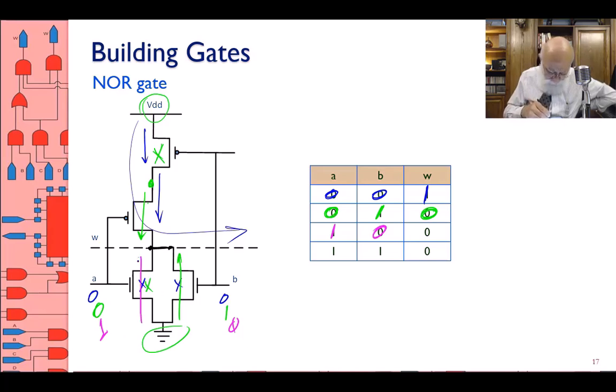Let's look at the 1 0 situation, and actually this is basically the same. So a 1 meaning that this is pushing a 0 through, a 0 is being there, and then this is not conducting. Let's look at the top. The top, because I have a 0, this is conducting. Okay, but then this is conducting. Now this is what I was trying to say before. The supply reaches this point. But then the A transistor, because I have a 1 on its gate, is not conducting.